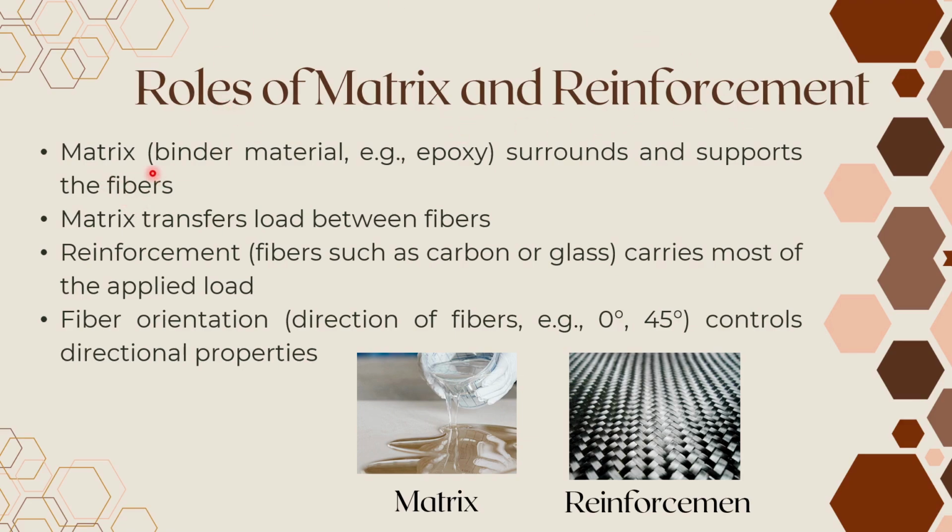The matrix, which I say is a binder material, epoxy resin, surrounds and supports the fibers. The matrix, the liquid resin, is responsible for transferring the load between the fibers. Mostly the fibers will be near each other, but there will be a gap through which the matrix will flow, and that will transfer the load between the fibers. The reinforcement, the fibers such as carbon fiber and glass fiber, carries most of the applied load because the reinforcement is the strongest one.